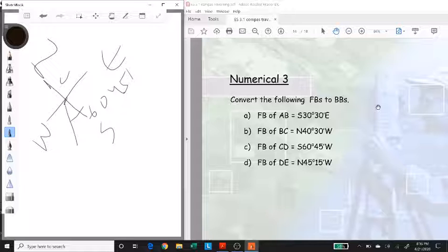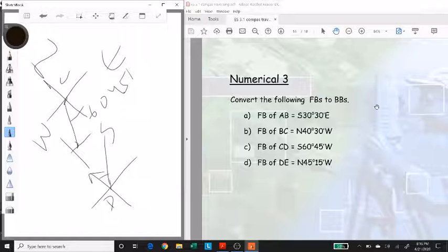And in order to see what the back bearing would be, we should make the grid over here at this point D. So I'm making it over here. This is point D, and the knots would remain the same. And for this continuation of the line, this would be the bearing. Now remember, in whole circle bearing, the angle or bearing always starts from the north clockwise, while in quadrantal bearing, it either starts from the north clockwise or anti-clockwise or from the south, depending on which quadrant we are talking about. So over here, this is the bearing that is under consideration, and this was the front end, and this is the back end.